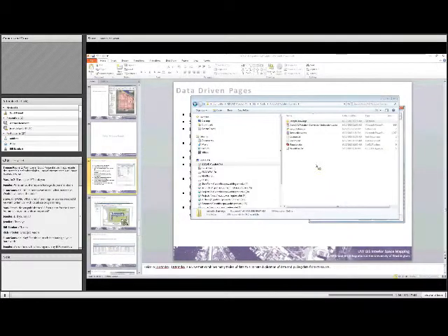We did do one sample project where we imported, through a variety of processes, a building that was done in Revit with all the assets and converted the assets into points. The data got split out and put into the asset management system that deals with all the data, and the location was put into GIS, and then the data was merged back together. So now we have a way of managing the data through the CMS, and a way of managing the location with GIS and the GIS floor plans. There's a lot of really great potential with that. It's just a matter of making it happen and getting that into everyone's daily practice.